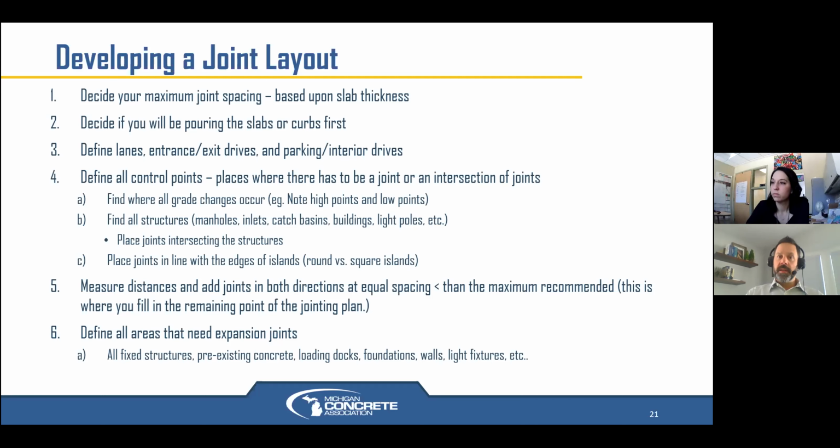Now, if you're pouring the slab first and you're gapping things out, it's the same thing. And if your joint layout is still not doing it for whatever reason, there's obviously a combination of factors that's causing that. It's hard to say without having more detail, but that's a great way that you solve that, as far as taking those tubes to form out those gapped areas, and then definitely using the flexible foam isolation material before you put that structure in that area.